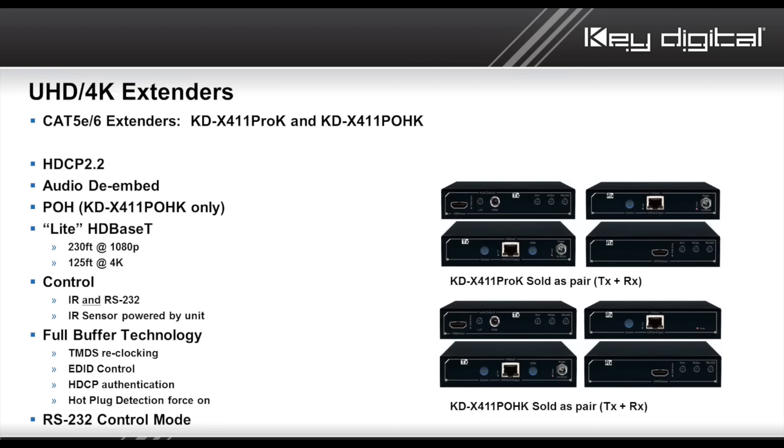So in the Lite HDBaseT chipset, to review, the X200 supports HDCP 2.2. The X400s have separate RS and IR ports and two different rotaries for control and EDID. The 411s support HDCP 2.2 and also give you an audio de-embed at your transmit unit. Now, that de-embed, very important to note, is not ARC, not audio return channel. This is a de-embedded signal of your HDMI input device, not audio return channel from the display.